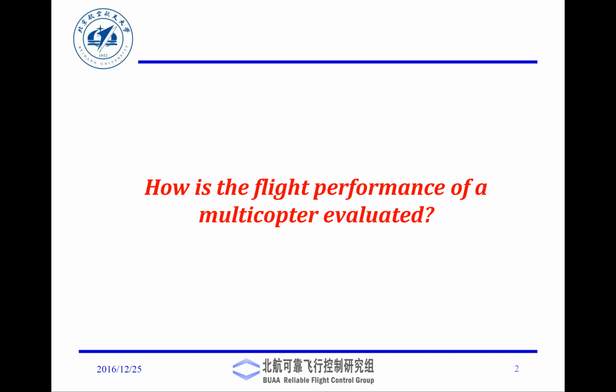Typically, brushless DC motors are used for quadcopters or multicopters in this larger size. If you are working with Mambo or Tello, the motors that you have are permanent magnet brushed DC motors. That's why you see only 2 wires coming in. They are very good for low speed or low power applications.